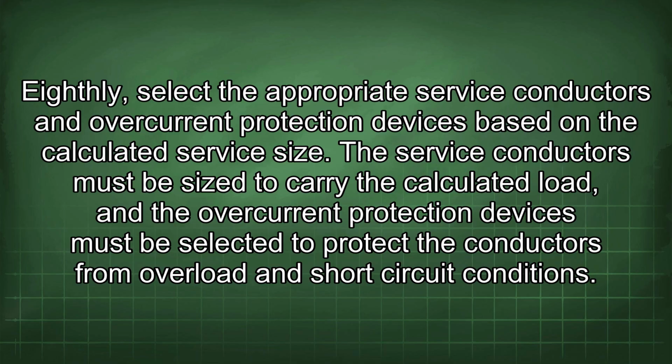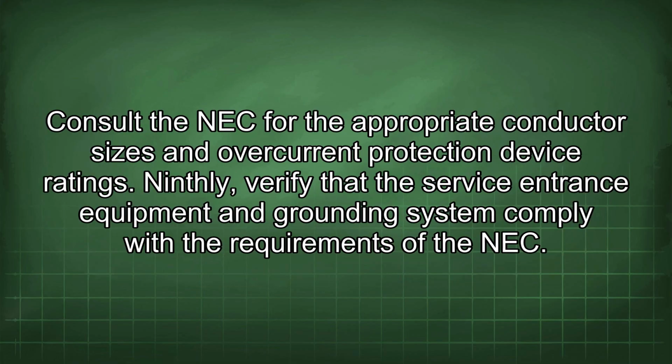Eighthly, select the appropriate service conductors and overcurrent protection devices based on the calculated service size. The service conductors must be sized to carry the calculated load, and the overcurrent protection devices must be selected to protect the conductors from overload and short-circuit conditions. Consult the NEC for the appropriate conductor sizes and overcurrent protection device ratings.